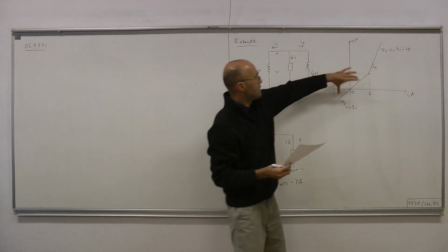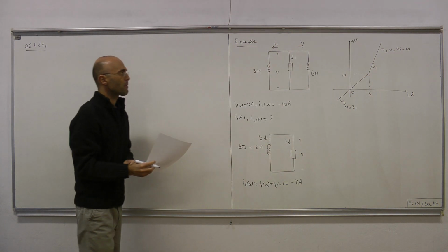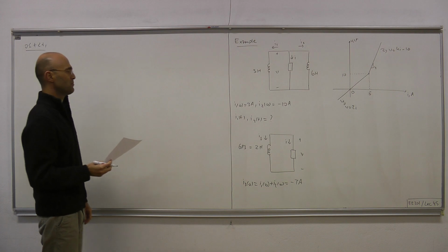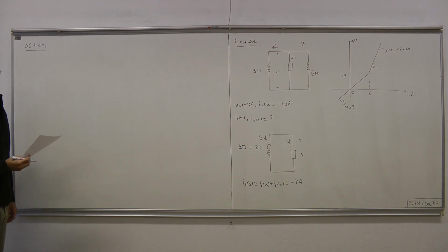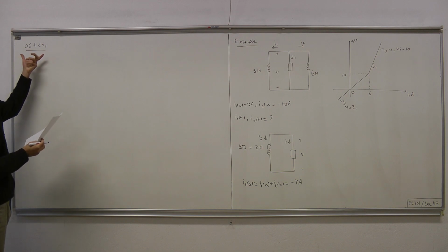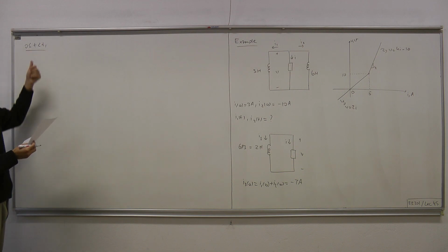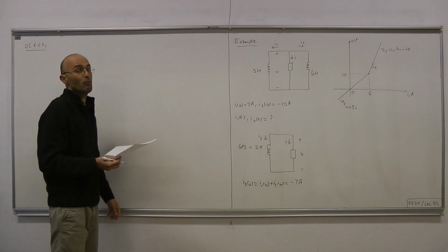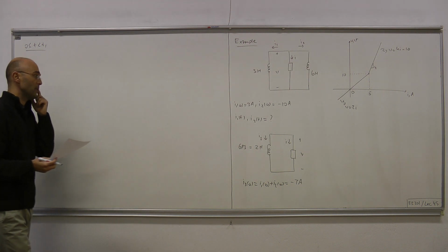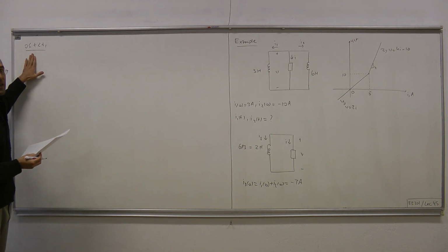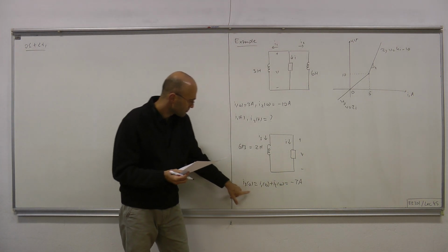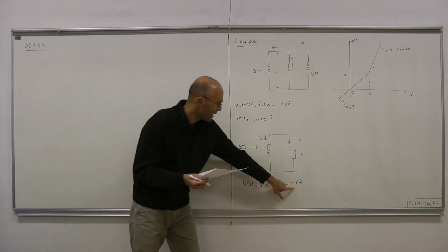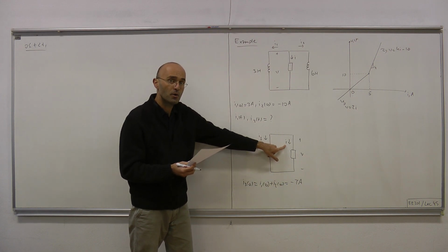Since we have a piecewise linear resistor, we are expecting a piecewise analysis. So the first piece is for the time between 0 and t1. Well, t1 may or may not be infinity, so we're going to figure that out later. But initially, let's see what happens. Initially at t equals 0, I3(0) is -7, therefore I(0) is 7.